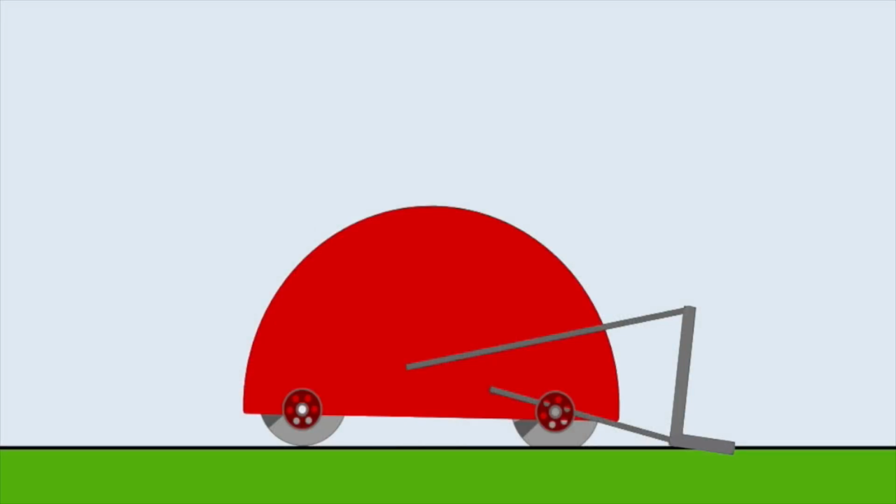So if you have a body that's rotating about some pivot, and you look at a point, so for instance, in this example, suppose we look at the link that would be connected at point A on the lifting mechanism, which is our coupler, and the other end is connected to the robot. So that's fixed at the pivot point on the robot. And to determine the velocity at point A, if it were rotating counterclockwise, then the velocity in the orientation that it's in right now would just be perpendicular to the radial line that goes from the pivot point out to point A. So right away we know the direction of the velocity.